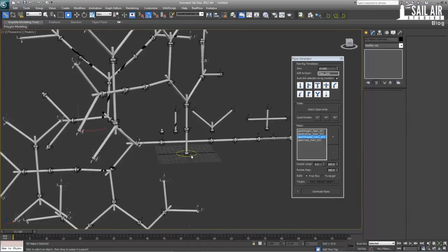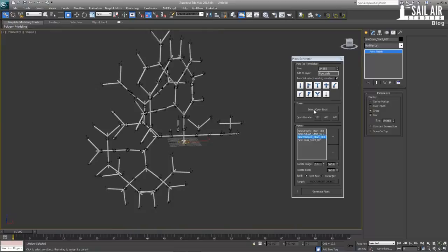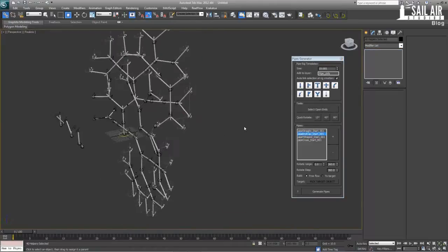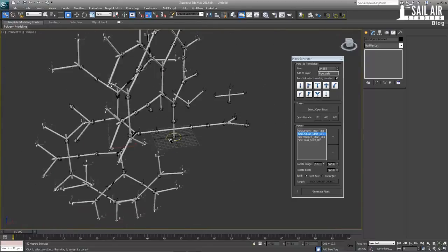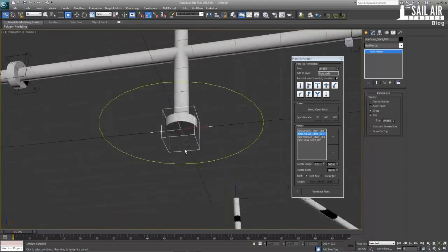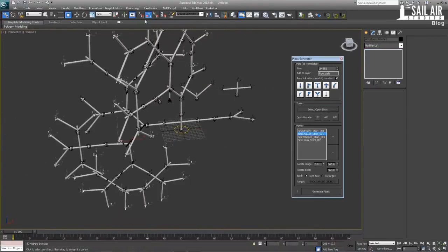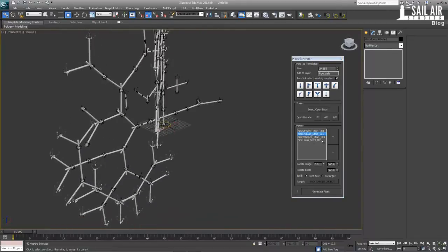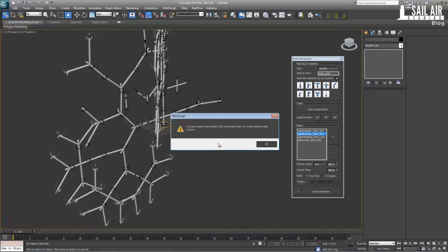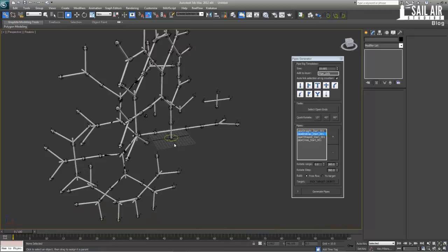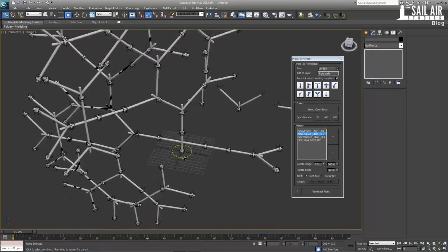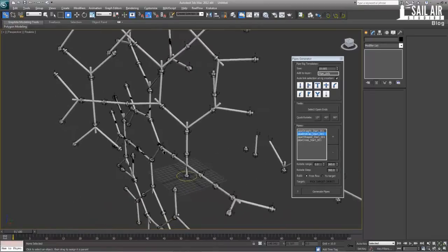Alright, so what it is: you select the beginning point of this entire sequence, select the open ends, and then it selects all the open ends of that sequence. Since it is sequential based, you need to select your starting cross thing, so your starting point. And then it looks through the entirety of the map, and you can quickly find it. We have a lot of open spaces here. We can quickly end everything at the end cap, generate pipes. And since it has the naming of the end cap, you don't want to change the names of the templates or anything. It will automatically know that the pipe is completed. And we have a quick pipe system made for us within a matter of minutes.